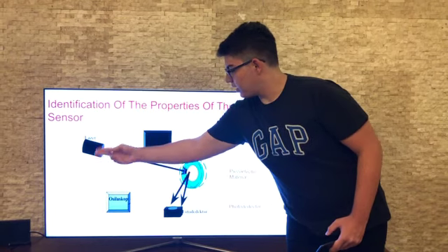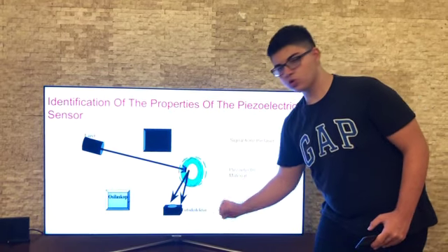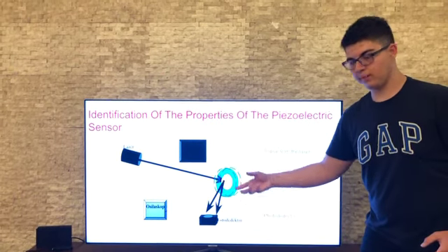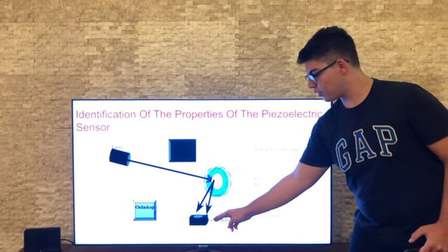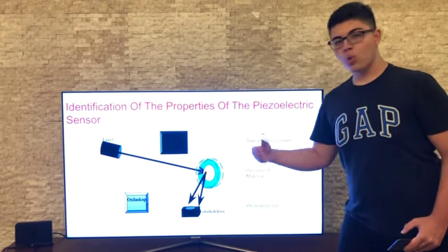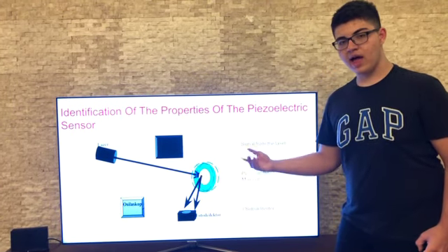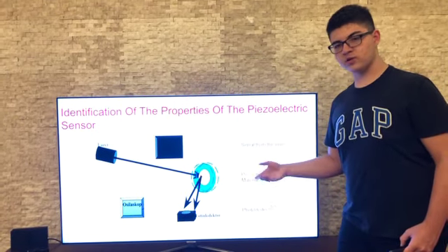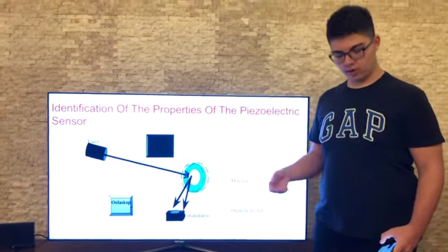A laser ray is sent to the piezoelectric sensor, which also gets reflected to a photodetector. When the laser hits, the piezoelectric sensor vibrates and moves. With this movement, the laser reflected from the piezoelectric sensor also changes its angle, and we can measure that change by the photodetector. Where the most change occurs is where the piezoelectric sensor vibrates the most, and thus we can find the resonance frequency, which we used for the frequency of the light we sent to the sample. And we measured that frequency as 3 kHz.